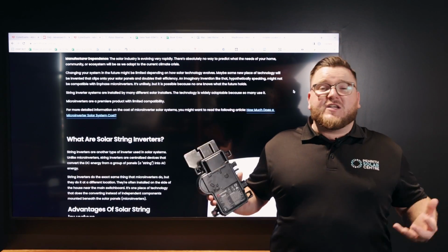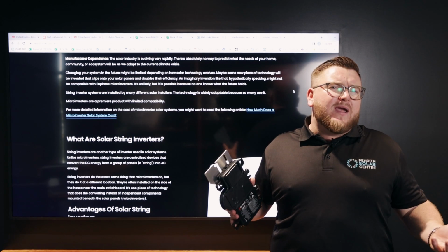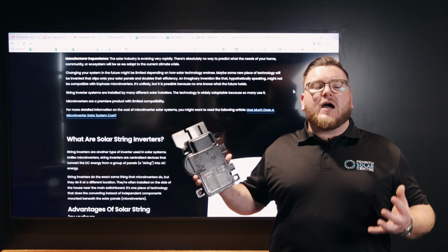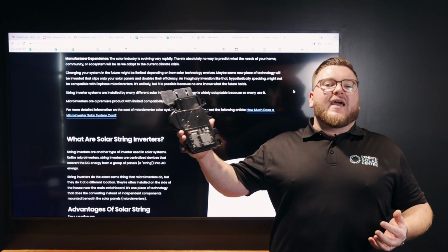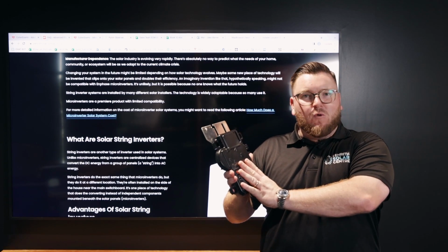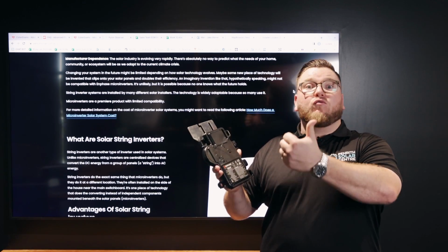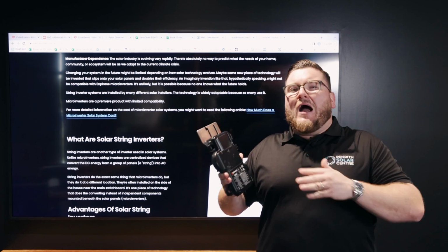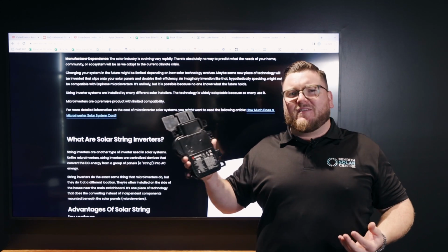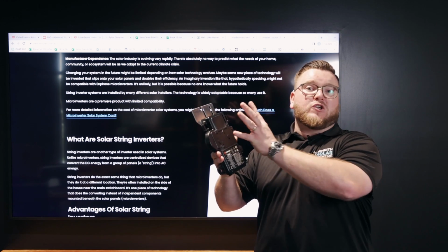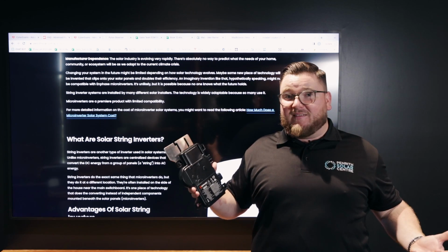The last disadvantage that we're going to speak about today, which could actually be an advantage for some, but a disadvantage for others, is manufacturer dependence. If you're installing Enphase microinverters, you must install genuine Enphase trunking cable, a genuine Enphase envoy, relays, as well as end caps and end plugs. Now, is it a disadvantage that you have to stick to the same brand, or is it an advantage that you're using quality products to match your quality microinverters that is going to stand the test of time? I'll let you be the decision maker of that one.